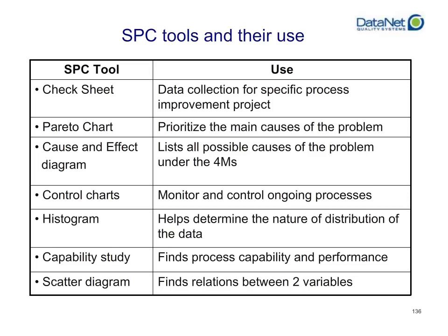Pareto charts help you prioritize which of those items in your check sheet should be the vital few that you should focus on, and using the Pareto rule, you'll be able to focus your time most efficiently for the best bang for your buck. Cause and effect diagrams allow you to brainstorm, based on the 4 M's, the possible causes of the issues determined in the check sheet and prioritized in the Pareto chart. The 4 M's, again, are man, material, machine, and method.